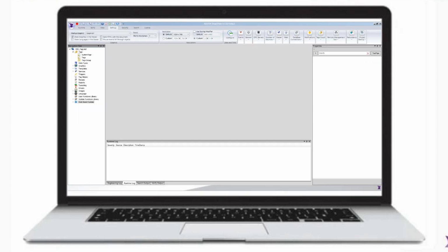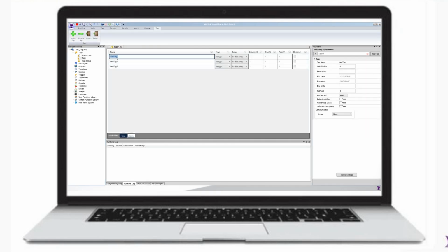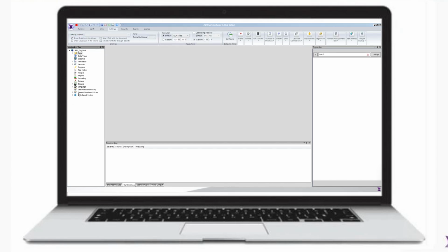The rule-based system can also be used to control simple tasks. Let's create 2 rules to control valve flow. It might be an alternative to the text box limits, which you will still see in this video, but using rules instead. To begin with, let's create 3 tags. The valve tag and the others representing the low limit and the high limit of the valve.